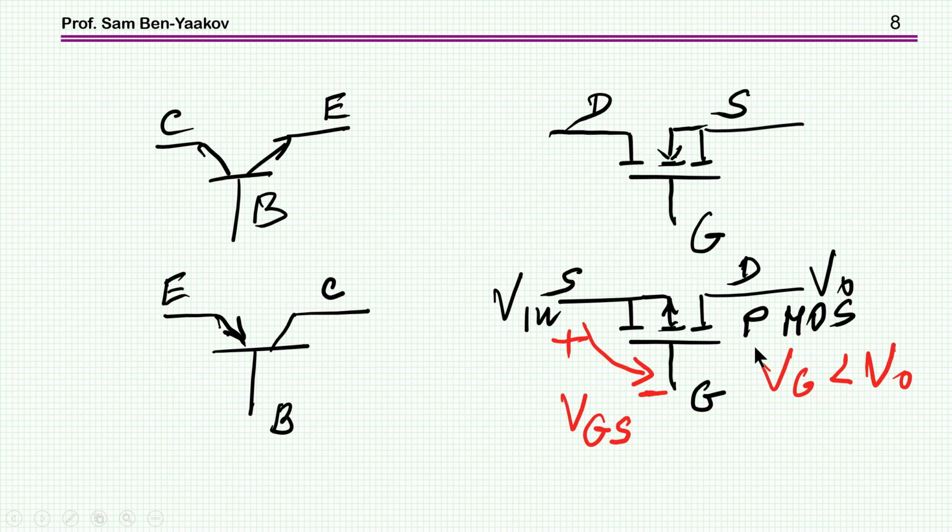If, however, the transistor is a PMOS, a P-channel MOSFET, then the gate needs to be at a lower voltage than the source. This would mean that if we have an input voltage, we can derive from it the gate voltage, which is lower than the input voltage, which is okay. So by this, we can actually accomplish a situation in which with a single input, we can drive the unit, and also we can achieve a low input to output voltage, that is, the difference is small.